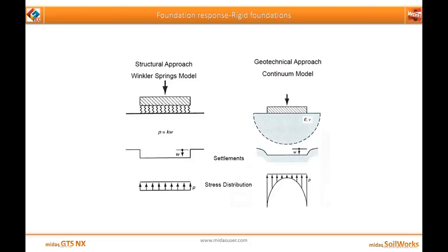That is, we have a very non-uniform pressure distribution with very high stress at the ends. And also in the settlement you can see that there is a curving at the ends. So that is also not considered when one goes for the structural approach, and this is how the foundation response differs whenever you are considering the rigid foundation.